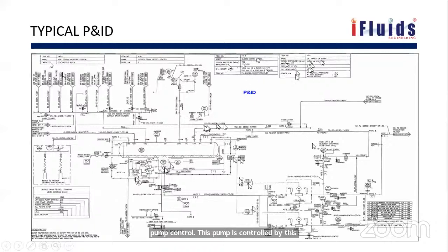So you have these drain lines, how all the instrument drain lines are connected. So everything is there. You have the PSVs, with PSV set pressure 630 kPa. You have this PSV inlet and outlet lines. So everything is clearly mentioned in the P&IDs. How to isolate this equipment? You see here the blind flanges for all the inlet lines and the outlet lines.